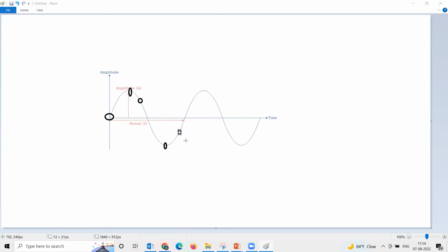When I say fault current, Ik'', that is the initial symmetrical RMS current, is changing. And we are talking about Ib asymmetrical, which is changing. IDC with respect to time, that is changing. All these things are changing. When these values are changing, my question is, why in ETAP are we not performing the short circuit studies with respect to different instants at which the fault has occurred?